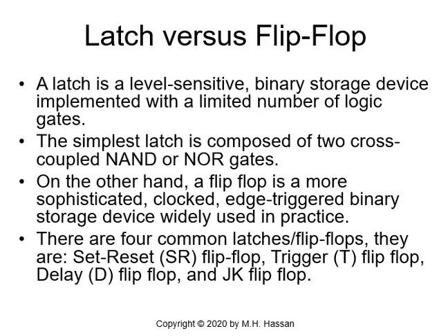On the other hand, the flip-flop is a more sophisticated, clocked, edge-triggered binary storage device widely used in practice. So it is not level sensitive like the latch, it is edge triggered. It is triggered either at the positive edge, when the signal moves from 0 volt to 5 volt, or at the negative edge, when the signal or the clock moves from 5 volt to 0 volt.